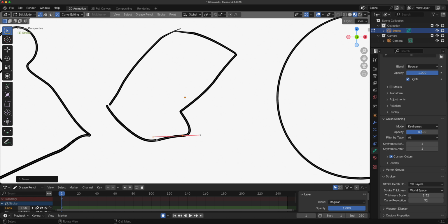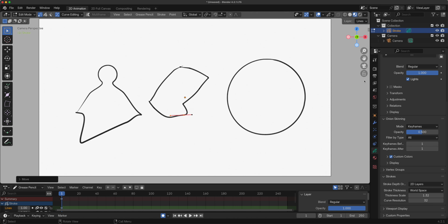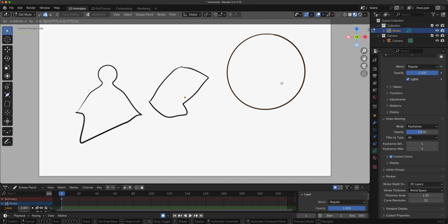All right, the most use of edit is when we're animating and we want sections adjusted and repositioned. But you can also go in edit mode, do, let's say, stroke selection. We selected this, turn off curve editing, okay? We can press G and move and position.